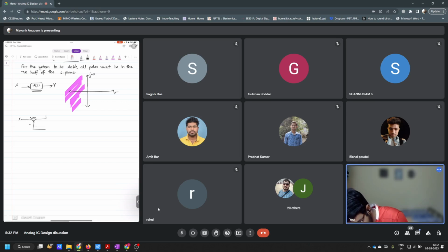Okay, cool. Now, in the lectures we saw, right, when we have a loop, this is x, this is negative feedback, let's say this is omega u over s, and here we had a resistor divider, right, (k minus 1) times R, and this was R, and this was V out, so this was V in. Okay, so when we had this system, this basically was the ideal system, right? This was the ideal system.